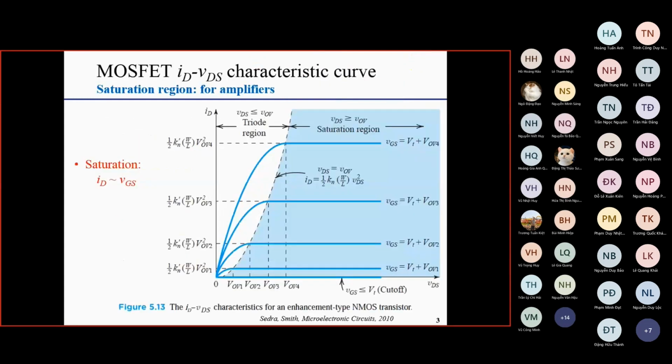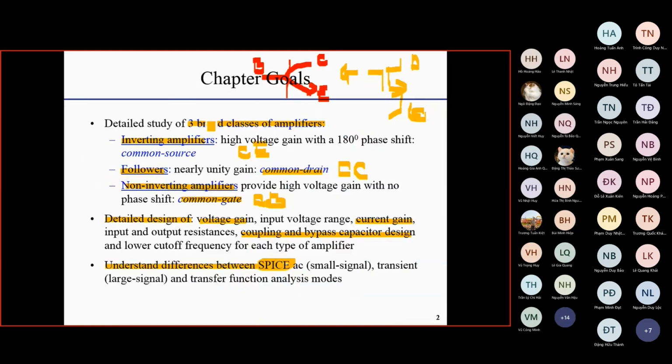We will go very quickly because it is very similar to the amplifier with BJT that we have studied. The only difference is how to calculate the biasing point, the Q point, which we have studied in the previous chapter. The small signal model of the field effect transistor is a little bit different compared to the BJT. This is the only difference. Otherwise, the procedure is the same: in the DC circuit replace capacitors by open circuits, in the AC circuit replace capacitors by short circuits, draw the AC equivalent, replace the transistor by its small signal model, etc. The whole procedure is always the same.